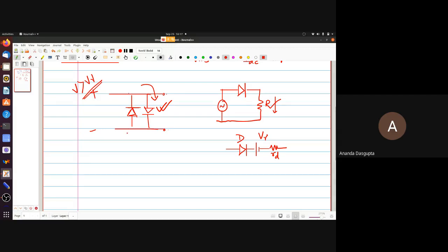Since it is connected in parallel to this strip, whatever voltage occurs across this, the same voltage must appear across this. Right? This plays no active role in changing or setting the voltage. Whatever voltage this forward-biased diode gives it, it happily takes. In reverse bias, the diode itself is off, so it plays no role in conducting or changing the voltages. But that's for one half of the cycle.